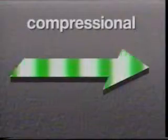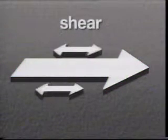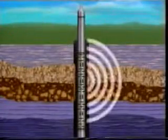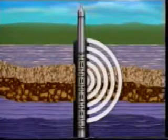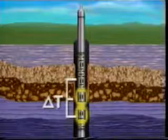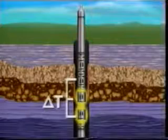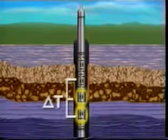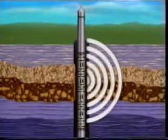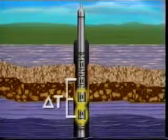The compression, or C wave, moves faster than the shear, or S wave, in any single solid medium, rock in this case. Consequently, the compression wave always arrives at a distant point ahead of its companion shear wave, and is the wave used in conventional sonic logging as the measure of acoustic travel time, delta T, from source to receiver. The time period from transmission to detection of the first arrival of the compressional wave is the measurement made in conventional acoustic sonic logging.